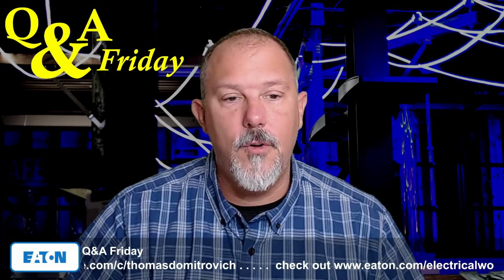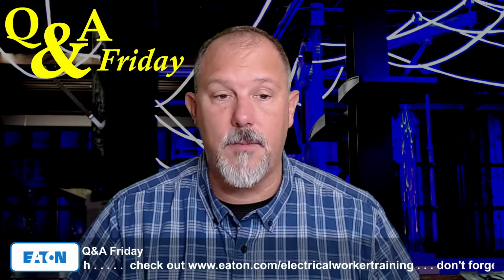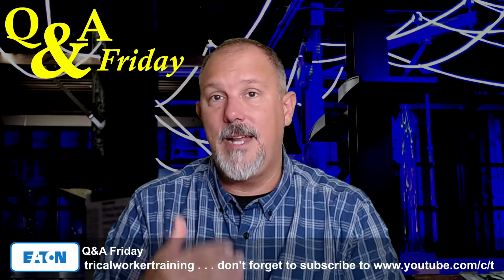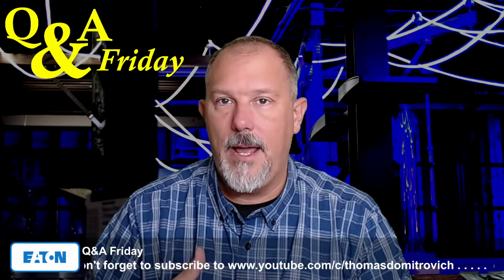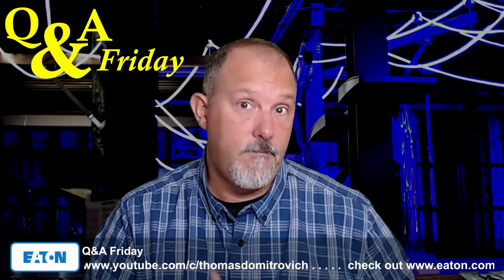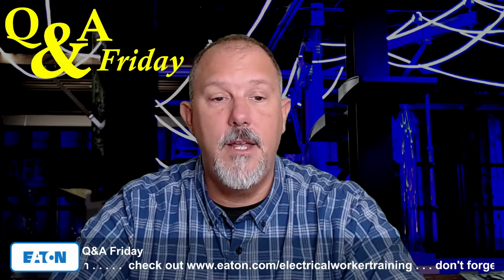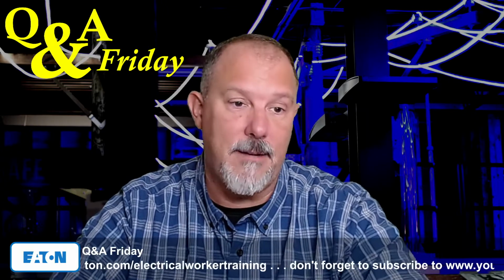So I will tell you that some of my panel boards will not accept 100% rated breakers. To be 100% rated, it's all about the temperature. It's all about getting the heat out. And if I can't rely on the conductor that you are attaching to my lugs, my terminals, then I have to get that heat out in a different way. Maybe it is the copper bus that I mounted in the panel board, right? Maybe it's different lugs. Maybe it's a different design of a device. But regardless, you make a very valid point that it is not about the device. It is about the assembly and all of the devices in that assembly.